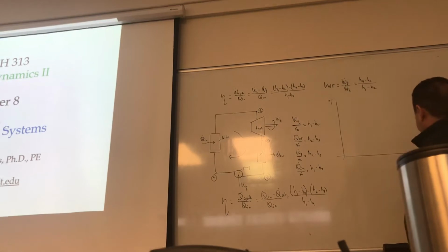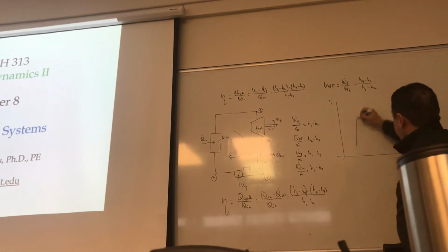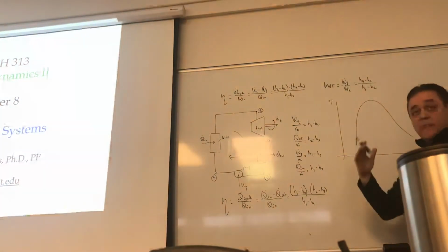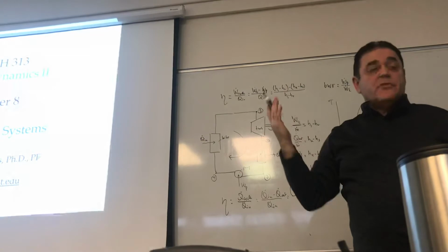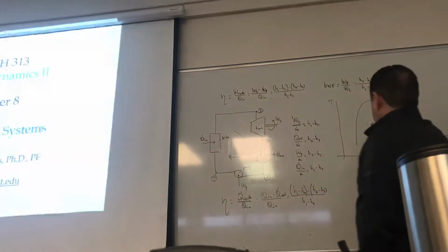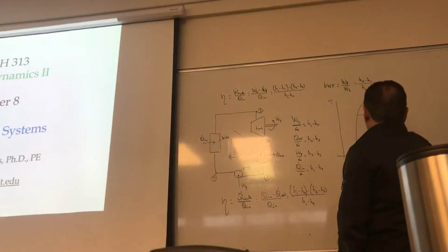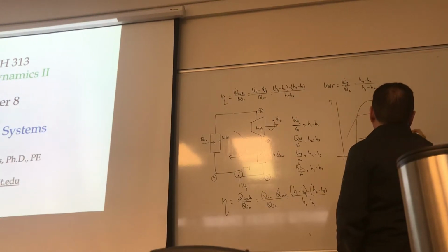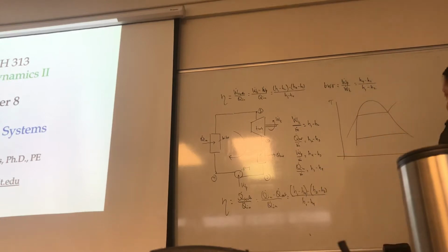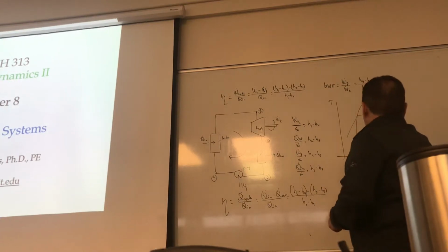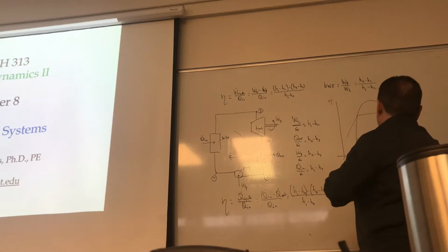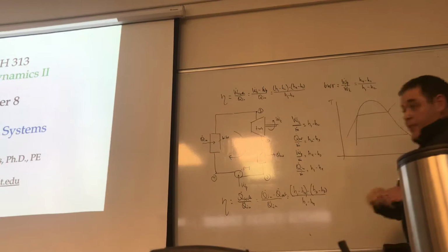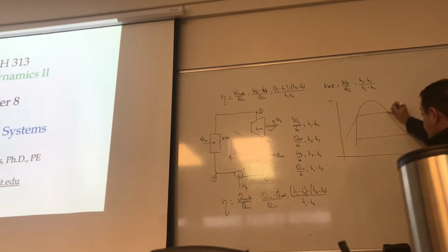So if you have this versus S, what we typically have is a dome like this, and we operate between two pressures, the high and the low. The high pressure is somewhere here. The low pressure is somewhere there. For a Rankine cycle, state number 1 starts right here.